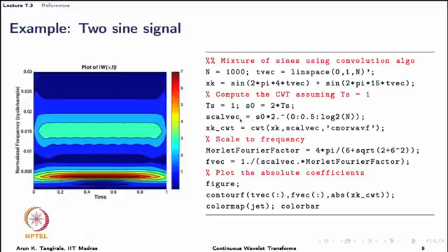Then the grid size is your choice. What I do here is I choose a dyadic grid size, but you could choose a linear discretization. This dyadic is keeping in mind that we will work with DWT in a few lectures from now. So, I choose a certain grid size and I go up to the length of the signal. Based on the length of the signal I choose my maximum scale. Remember, the maximum scale corresponds to the lowest frequency. Ideally, I should not be even trying out log 2 of n, I should be trying even lower scales, because you may not be able to detect frequencies as low as corresponding to this maximum scale, but it is okay for illustration.